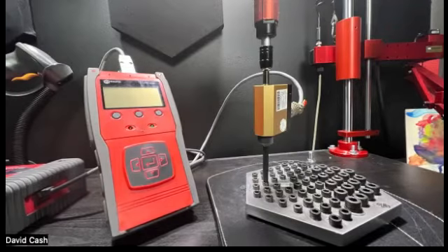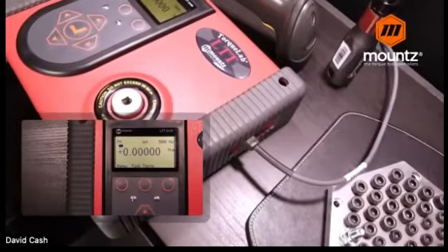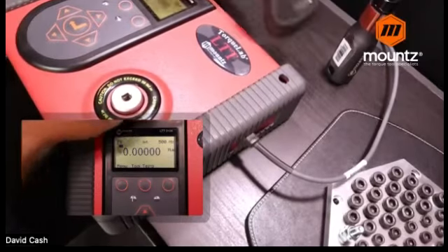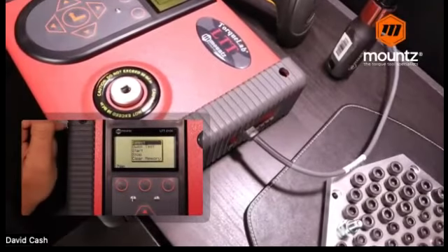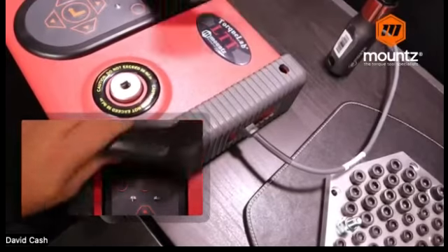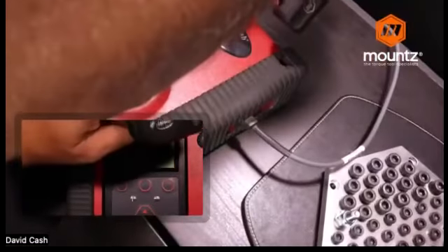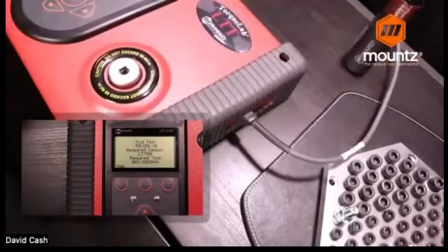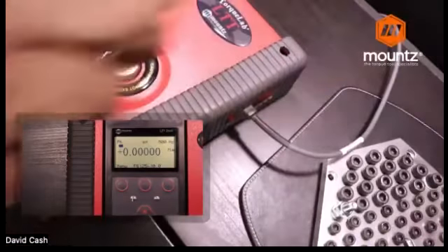Now, we do also have another function that is very useful in this, and that would be the use of a barcode scanner that can be hooked up to the analyzer. And so in this case, we have our tool here with a barcode. We can go ahead and activate the barcode by the use of our tool test function, and then we can hit select test. This is going to power up the barcode scanner. Then we can simply just grab the scan of the tool. That's going to automatically set up a tool test that we have already pre-loaded onto the unit.